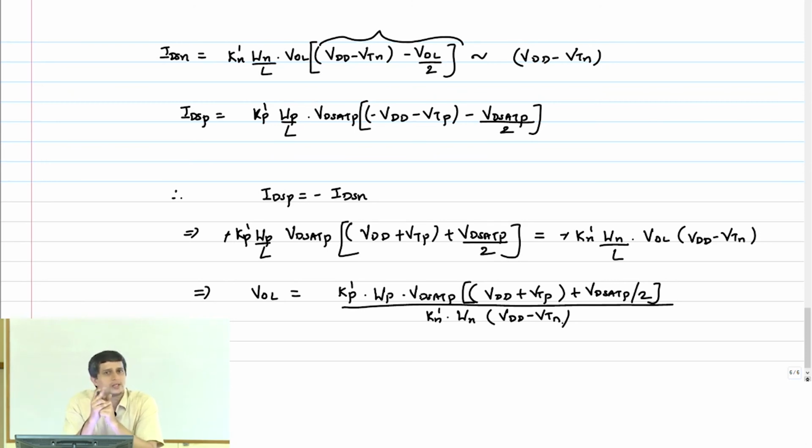Earlier I had mentioned that static CMOS is independent of gate size as far as logical functionality is concerned. It will work whatever size you put, whether you put 1/2, 1/4 or 10/1, it doesn't matter, it will function correctly. It's only for delay purposes that we actually made it 1 and 2 and all that stuff.